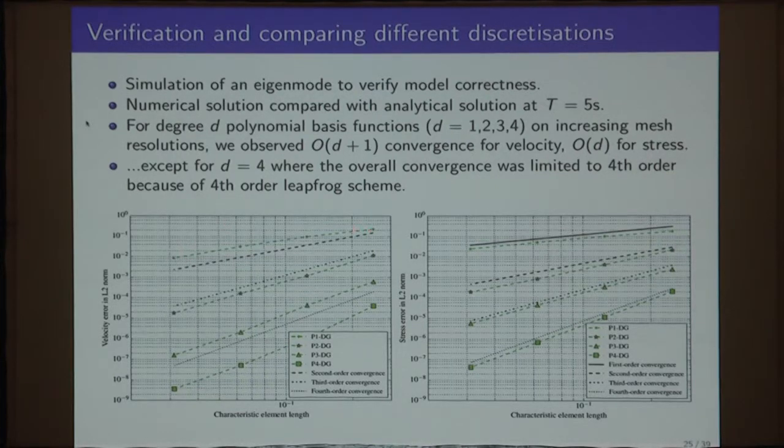So we can see that first order schemes have a very low order of convergence, and you can see the error that it reaches. Basically, as you start increasing order, the convergence rate is faster, as you'd expect, and you achieve a much more accurate solution. This is pretty much all that you expect. The two diagrams here are actually the same, just one is for velocity and one is for error. So it shows that everything has the order of convergence that you expect.